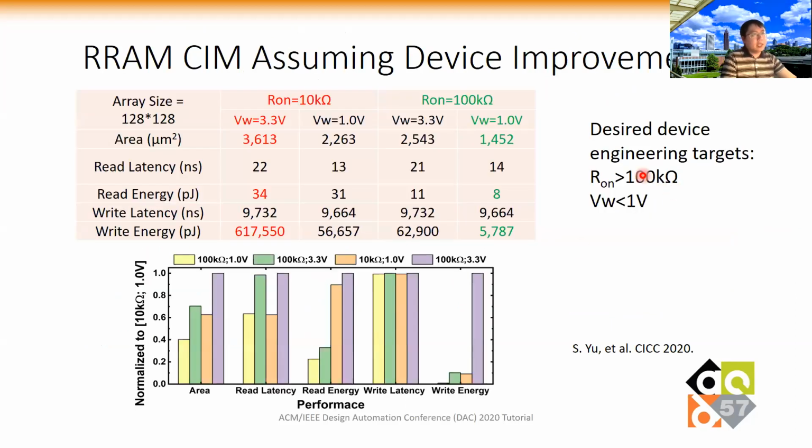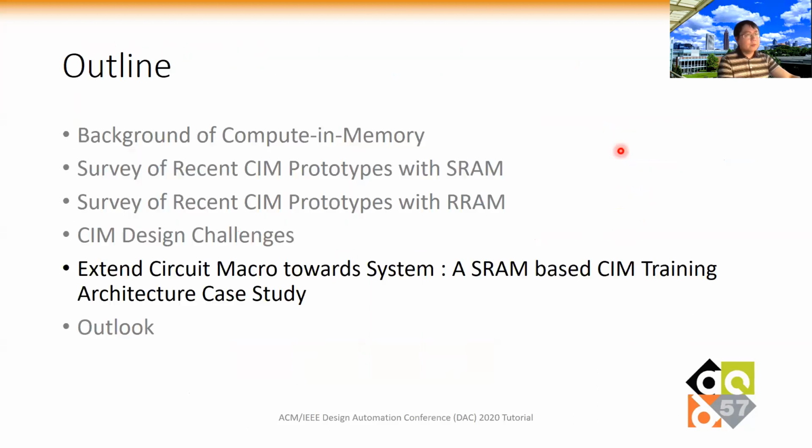So here, the desired device engineering targets will be on state larger than 100 kilo ohm, and the write voltage compatible with the logic, for example, 1 volt. So this still needs the device engineering efforts.